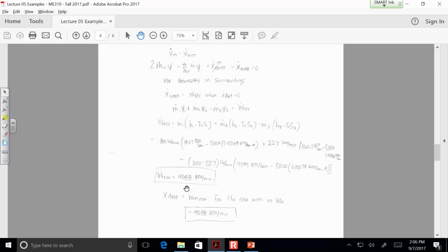And then when we go to determine the Exergy destruction, we also look at it with the system boundary outside the system. So we're looking at the irreversibilities of the system, and we find that all of the Exergy that is available to do this work is destroyed because we just mix these fluid streams together and we don't actually produce any work. If there were boundary work in this problem, or some shaft being turned, or something else happening, then our Exergy destruction would not be the same as our reversible work. But because we're not doing anything useful with this system, they are equal to one another.